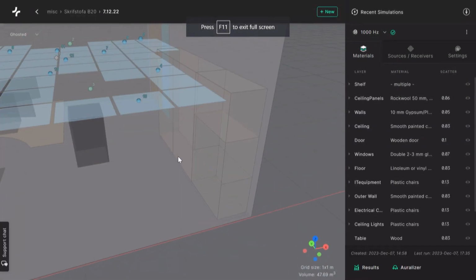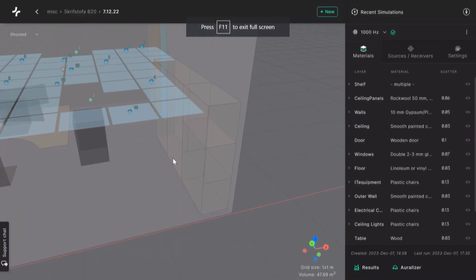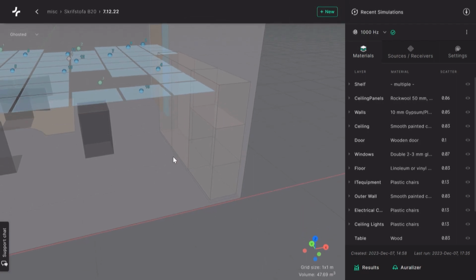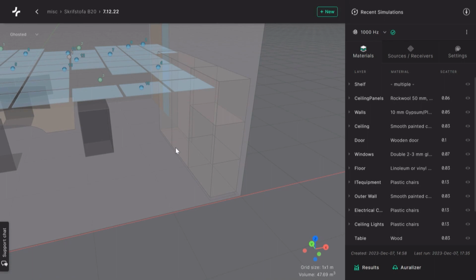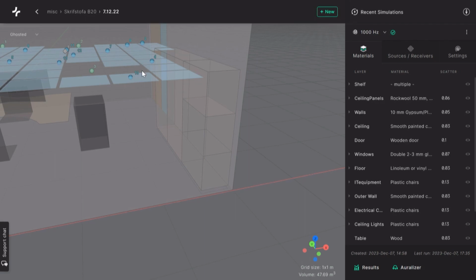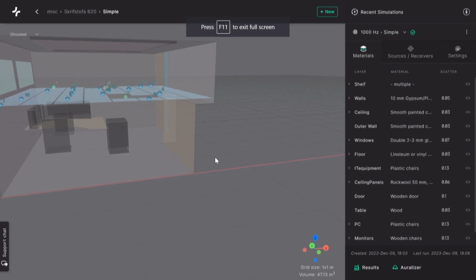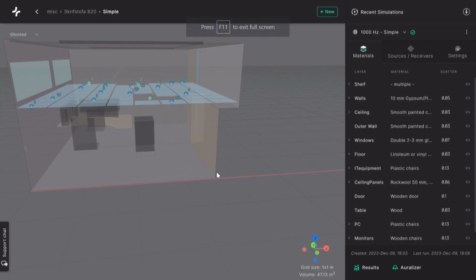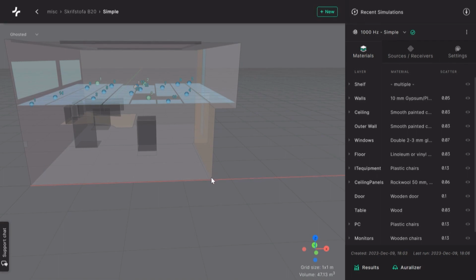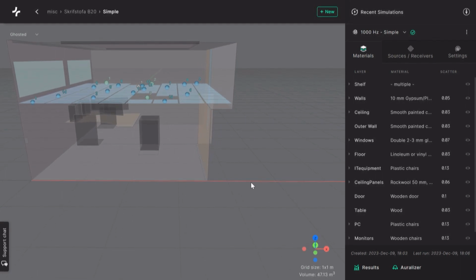we can think about, well, the logical next question would be, what if you just create a hybrid material for the front of the shelf that has the low frequency absorption characteristics of the gypsum wall and the high frequency characteristics of the shelf? Well, the problem with doing that in a model like this is that you have changed the location of the boundary and moved it into the room according to the depth of the shelf itself. So in this case, we have a 40 centimeter deep shelf and a 4 meter wide wall.